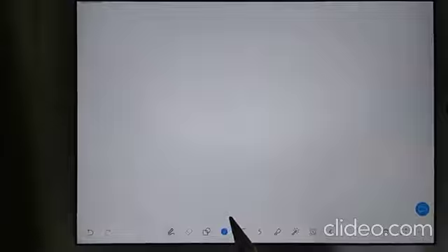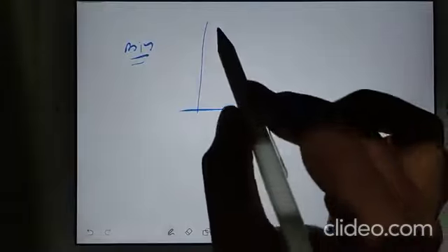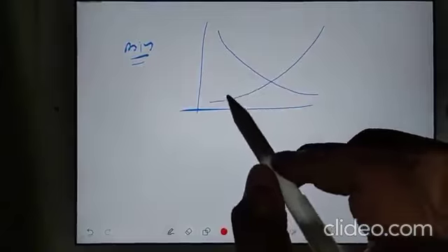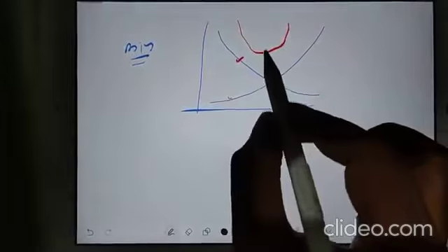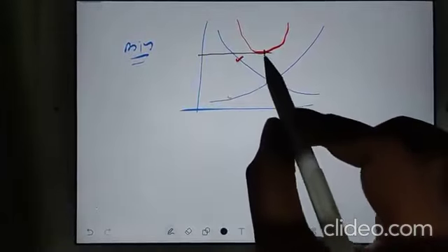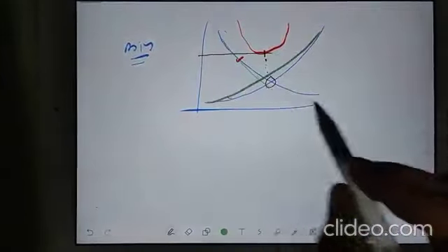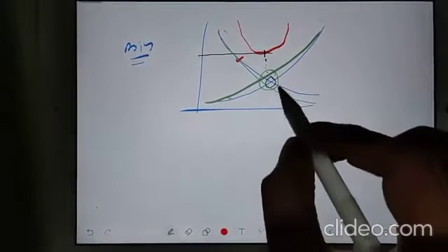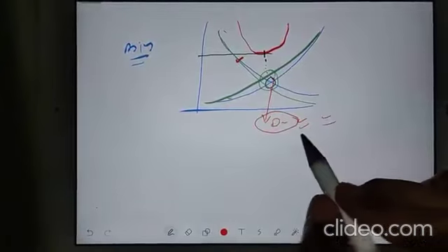When we were talking about minimum drag condition, we saw this graph: this drag is here, this drag is here, and we understood that because of these two drags we have the total drag like this. And then we saw that at this point your total drag is minimum, so this point is nothing but this point. It means this line and this line have equal coordinates here. So you can get the physical feel that both the drags are equal here. So minimum drag is the condition when both the drags are equal.